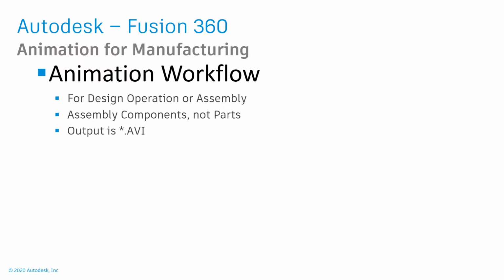And a note to keep in mind, this is really for working with assembly components, not for part bodies. So if you have a multi-body part, animation won't really work for you because it doesn't let you move those parts around freely.